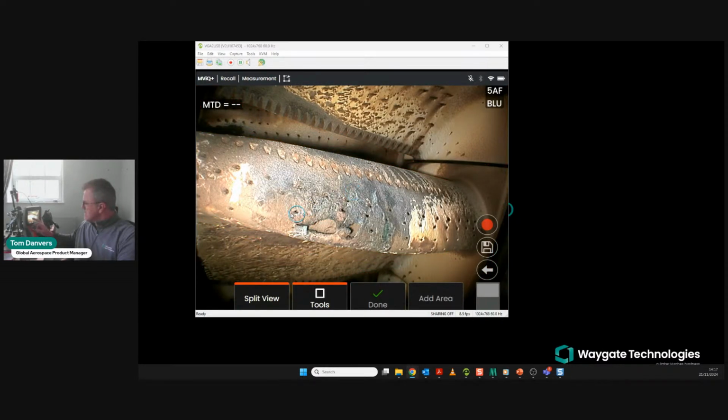So I've selected auto box, and what I'm going to do is scan and determine the area of the missing material first, as opposed to oxidation first, because by trial and error, you'll realize that it's better to work in the center and work your way out. As you work your way out, the areas of the resultant defects that surround the inner area don't overlap. So the area for oxidation is not including the area for missing material.